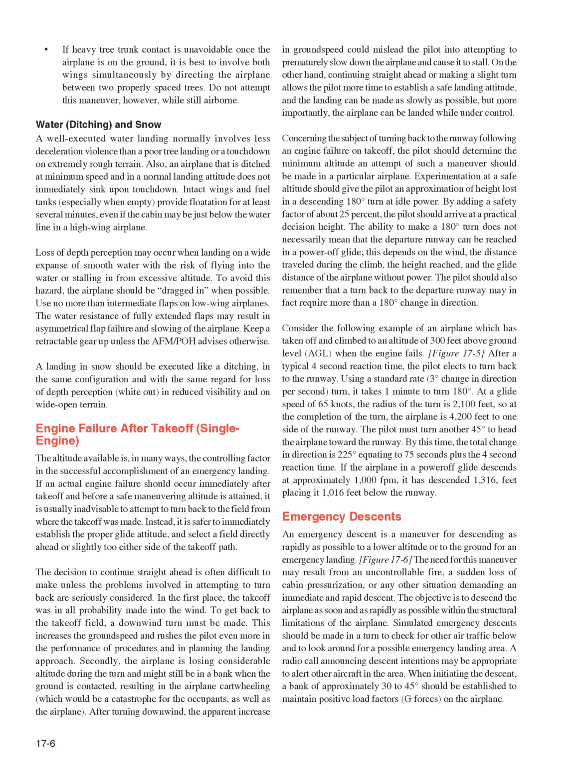Consider the following example of an airplane which has taken off and climbed to an altitude of 300 feet above ground level (AGL) when the engine fails. Figure 17.5: after a typical 4 seconds reaction time, the pilot elects to turn back to the runway. Using a standard rate turn, 3 degrees change in direction per second, it takes 1 minute to turn 180 degrees.